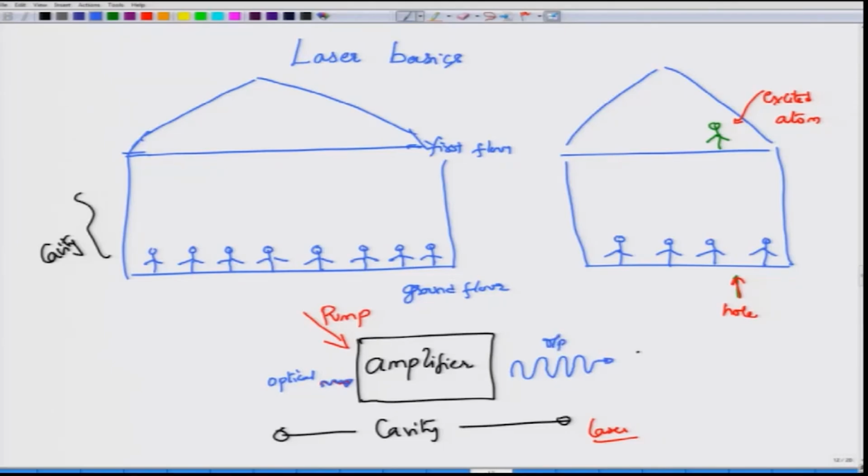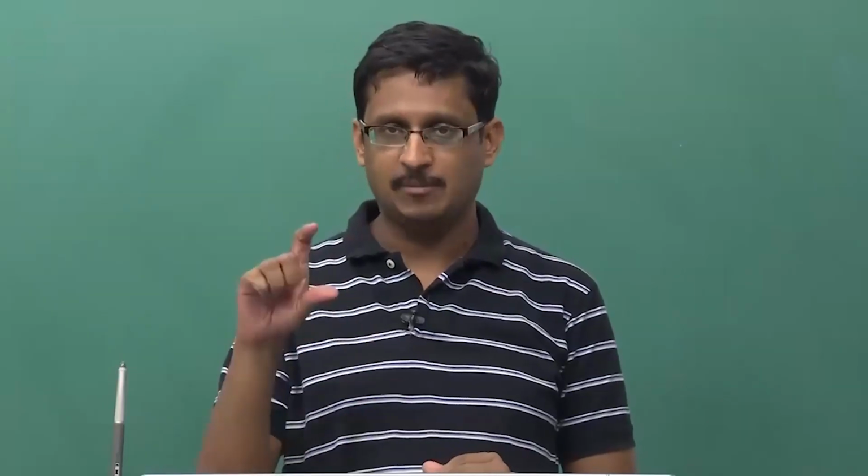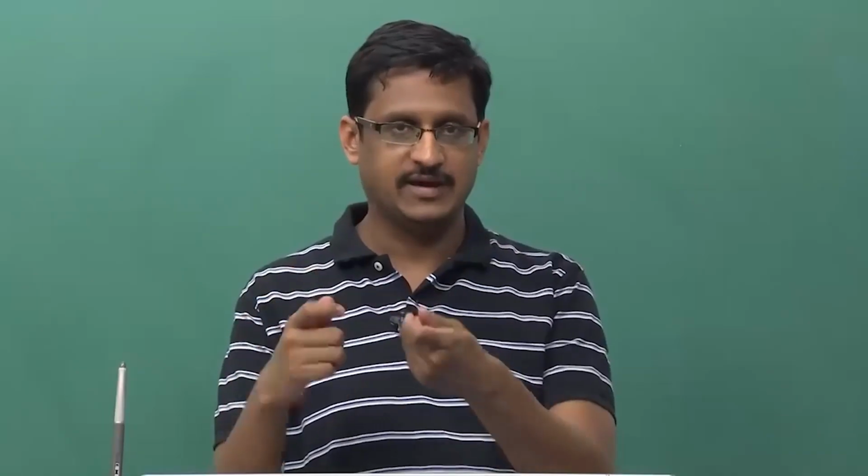In fact, the ideas of amplifiers and oscillators, and a laser is essentially an oscillator, are not something new. You have already studied this in your electronic circuits. You have studied perhaps the Hartley oscillator and Colpitts oscillator, and if you look at the circuit diagram of those oscillators, you would find that there is an amplifier and there is a pumping source. The pumping source, or the external energy, comes from the DC power supplies that you connect to the amplifier.